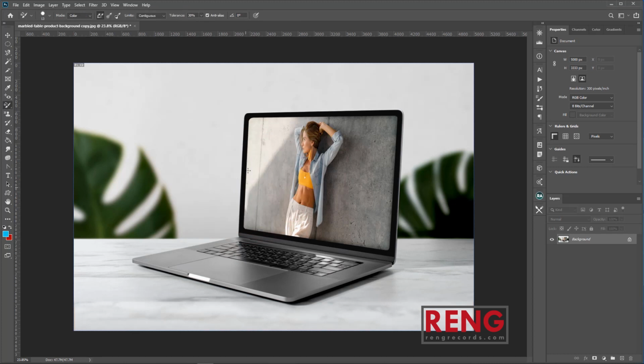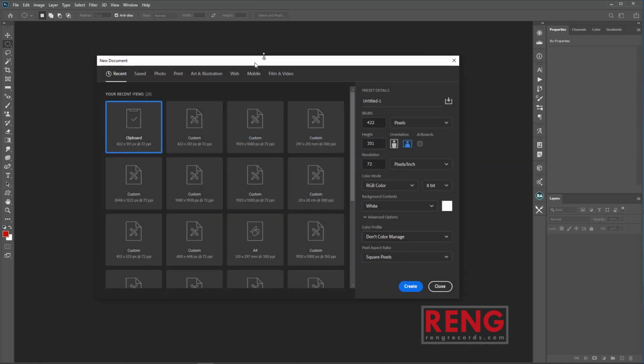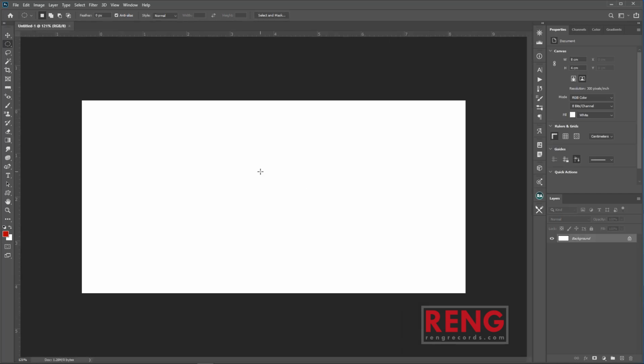If you are going to design a visit card or a banner, as you know, you should be aware of how to use the ruler tool. Well, I will not take your time any further and will introduce the ruler tool. Number 1. Open Photoshop and create a page with the desired dimensions. Number 2. Enter the dimensions of the new page as desired and click the OK button. Number 3. Select the rectangle tool and draw 3 squares.